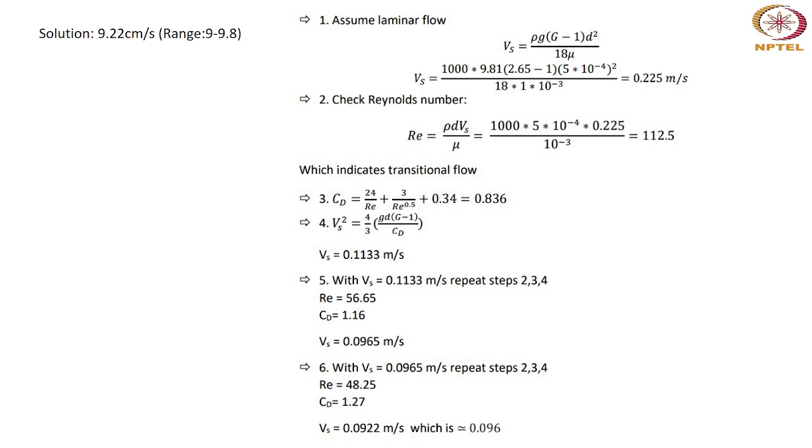At 4 degrees temperature only, we get this value. So in case of water also the density changes, and the viscosity will change. But if there is no mention of any temperature, you can just go with that. In most of the questions you will face, or real life situations, there will not be much variation. So you can just go with some fixed value.